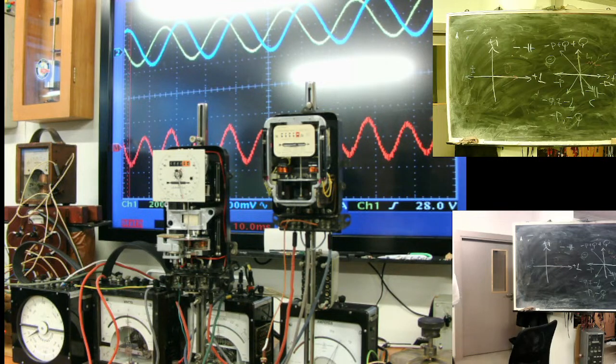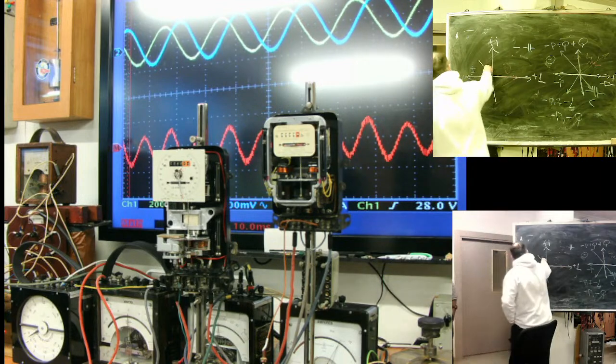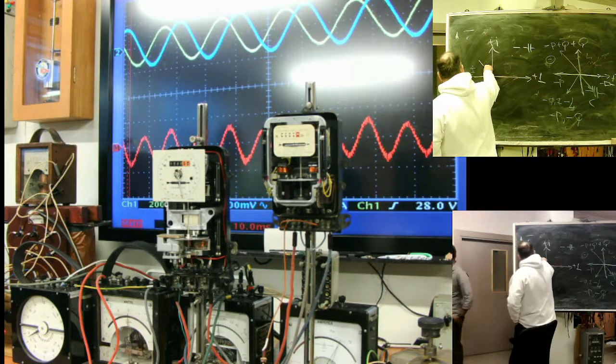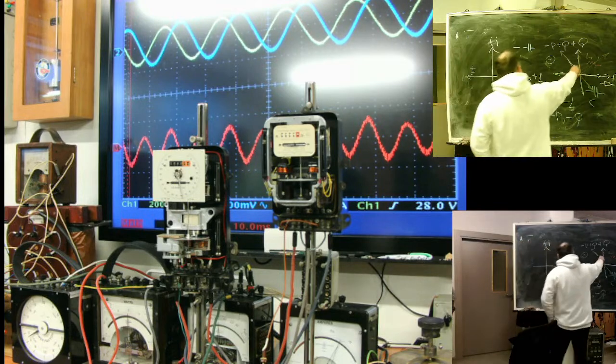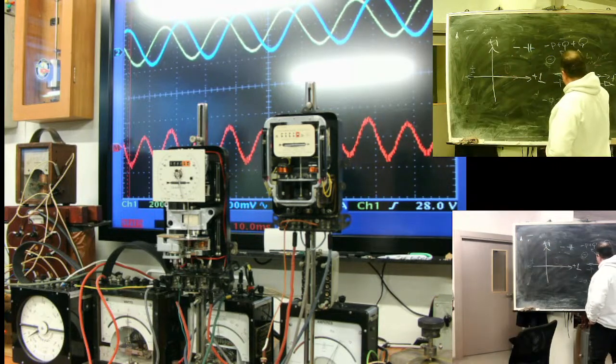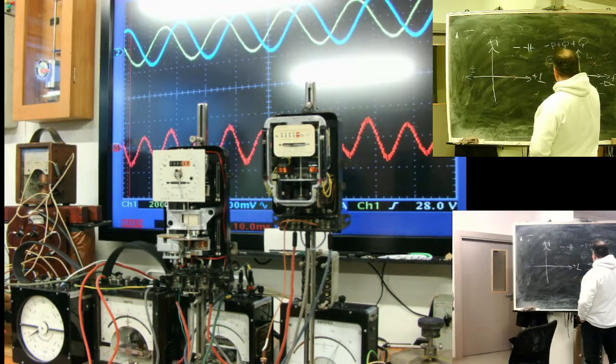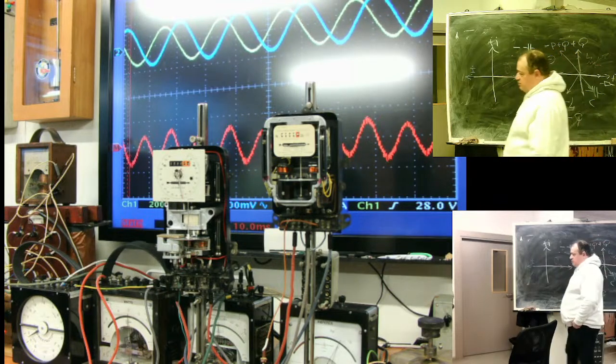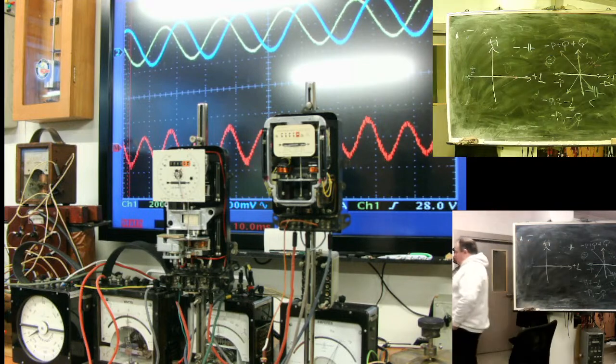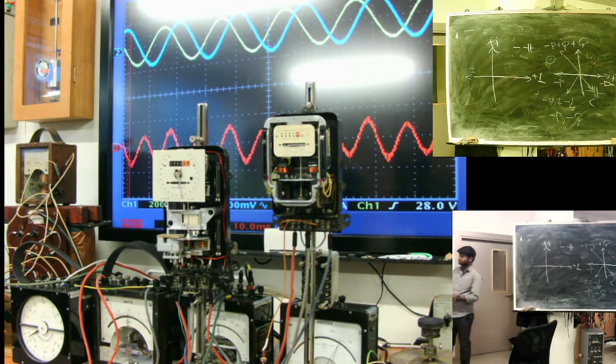You have mode plus Q minus P. It's this one. You send active to the network, but in the same way you take reactive from the network. Plus we consume. And you see meters go in opposite directions.